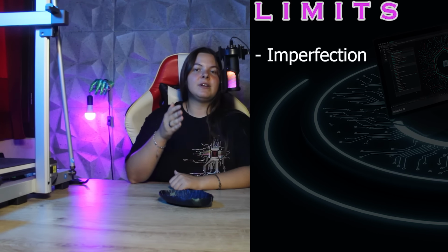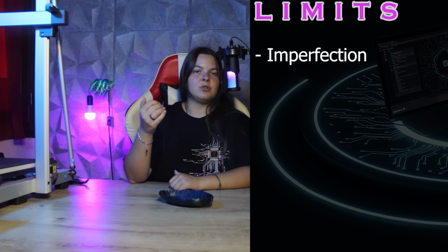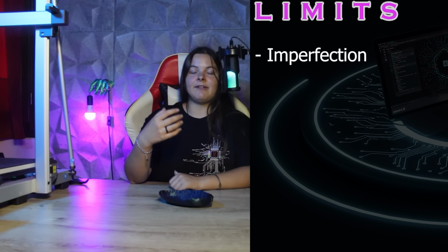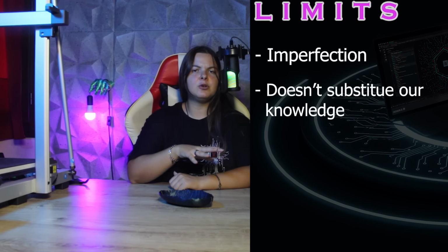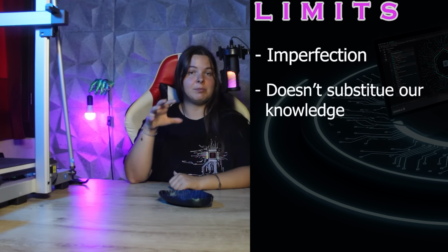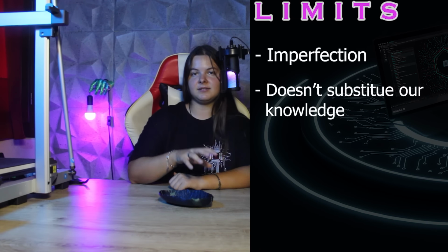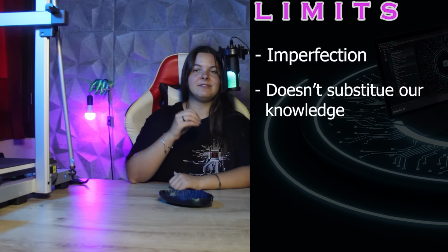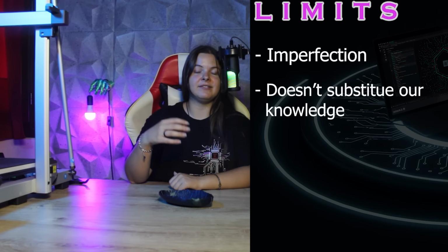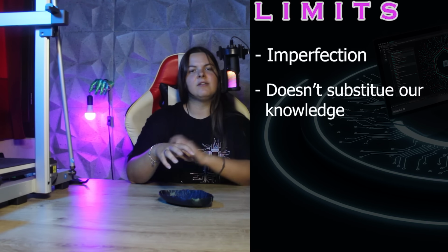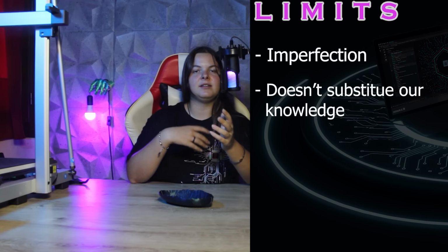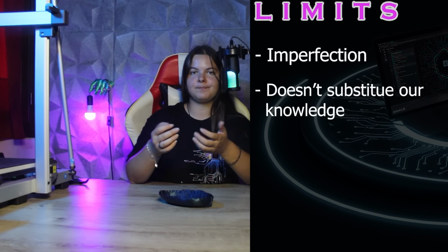But what are the limitations of this website? More complex or detailed models may have imperfections related to the maximum resolution of the model and the quality of the reference photo. Furthermore, this generator does not replace our 3D printing skills, because we will have to figure out how to best prepare the file for 3D printing, for example by cutting, rotating, or adding supports.